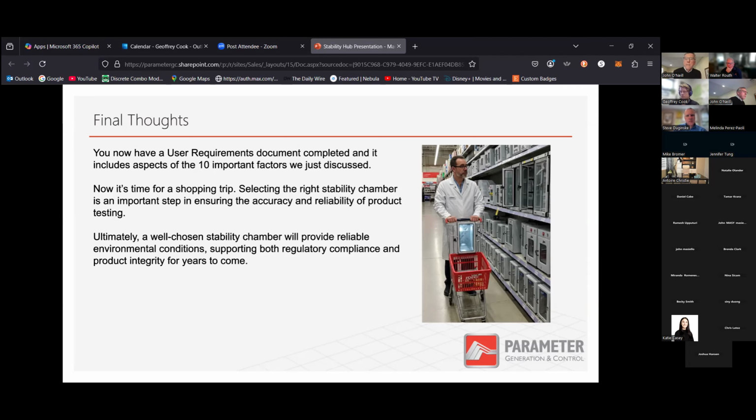Is there any sort of inline cleaning, to clean the air before it goes in the room? So we do use various filters, depending on what your needs are. We can look at HEPA filters. We can look at off-the-shelf residential filters. Sometimes a residential filter, if it has a cardboard frame and a cotton-based filter, it can actually be food for mold. We do put UV bulbs in our plumbing to help with algae growth.